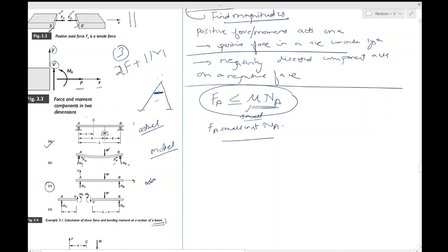so that the only reaction forces at A and B are in the vertical direction. We have also neglected the weight of the beam. The argument is that it must be very small compared to W, and that's why we are ignoring the weight.